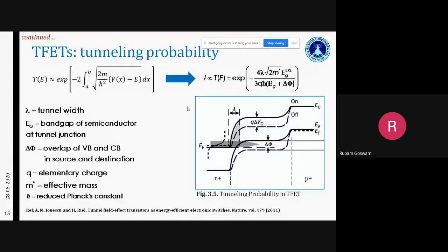So this is one of the key aspects why people go for heterojunction devices, and they use mole fraction dependent semiconductor materials like silicon germanium, and they try to modulate the band gap and other properties. And silicon germanium also becomes very advantageous because they belong to the same group as silicon, and this also facilitates the fabrication processes. So the tunneling probability is one of the key parameters for understanding TFETs from the quantum mechanics perspective.